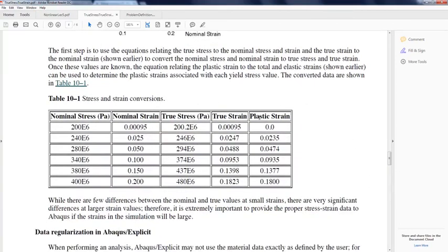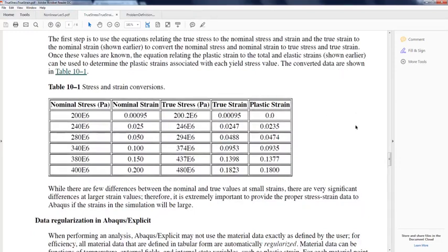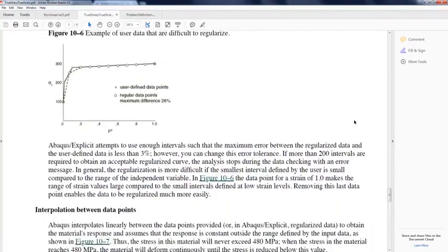The plastic strain here is a scalar measure. Remember that in the class, we have plastic strain being a tensor. It should have 6 unknowns, but we have simplified the problem, the plastic strain, into a plastic multiplier lambda and the direction m. M is in this case the tensor, and lambda is a scalar. And here this plastic strain corresponds to our lambda. These are the things I would like to highlight on this document.